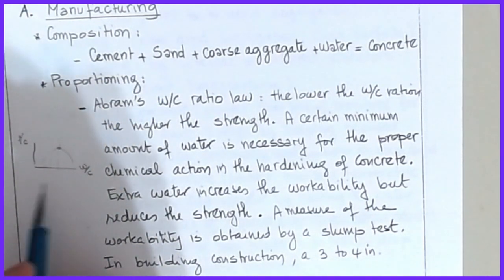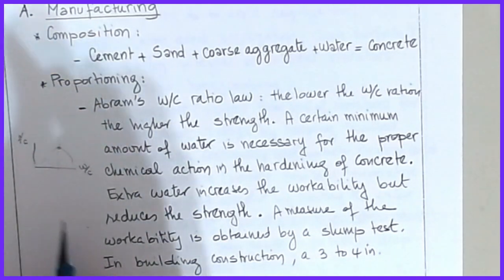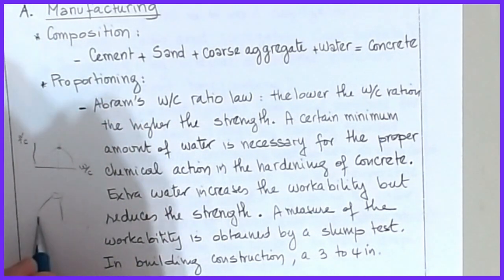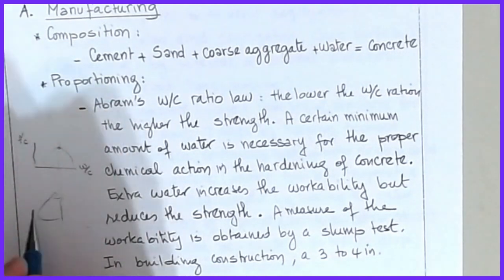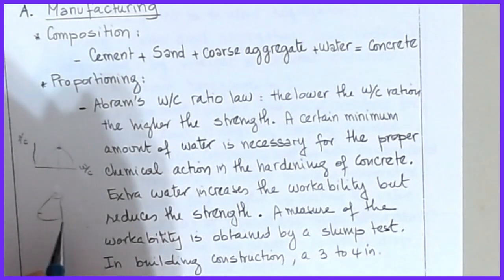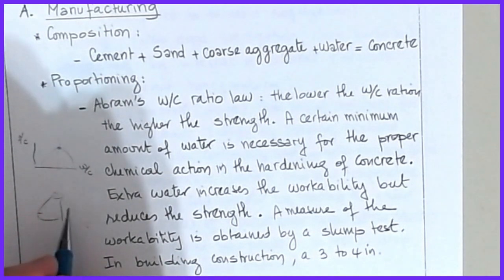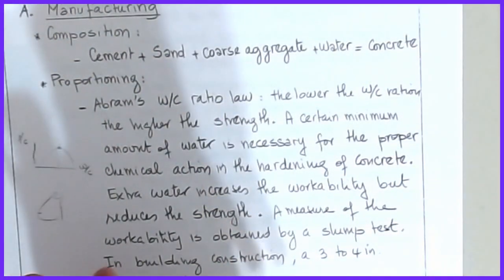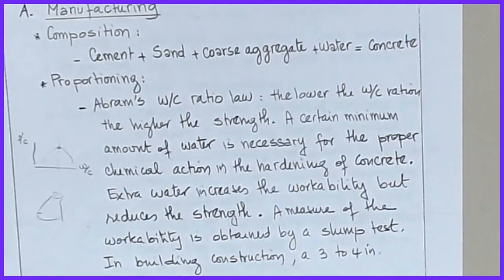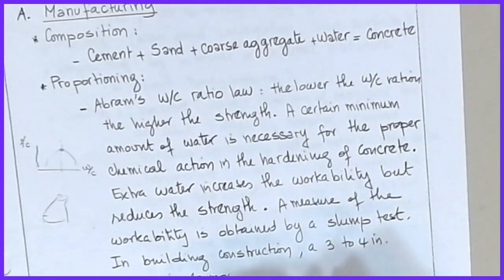One measure of the workability is to do what we call a slump test. Basically, I have a cone structure and I put the concrete into the top of the cone, and the cones have a standard set of dimensions. Then when you pull the slump cone off, the pile that's inside the cone falls a certain amount before it stops. You can measure it: it's a 2-inch slump, meaning that the peak of the cone came down 2 inches, or it's a 3-inch slump. It can be a measure of the workability. Generally, the higher the slump, the better the workability.